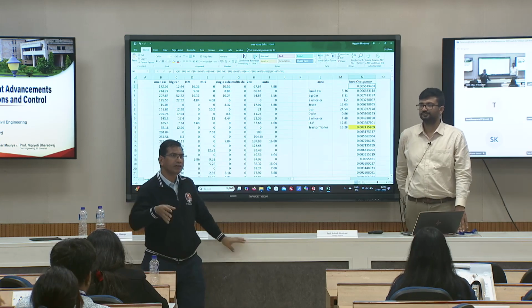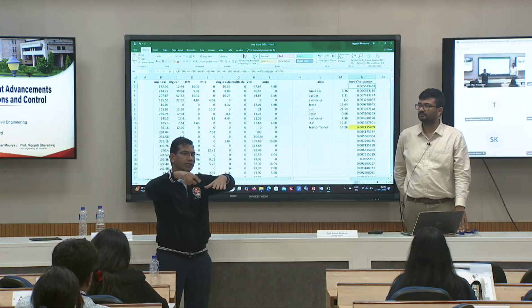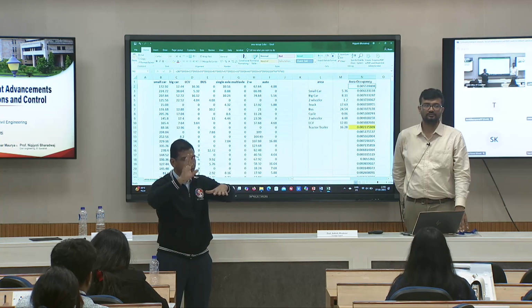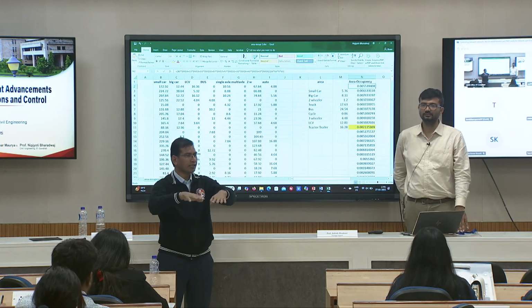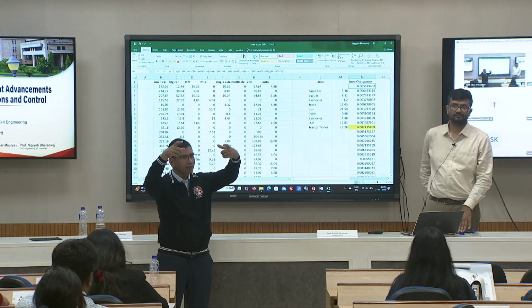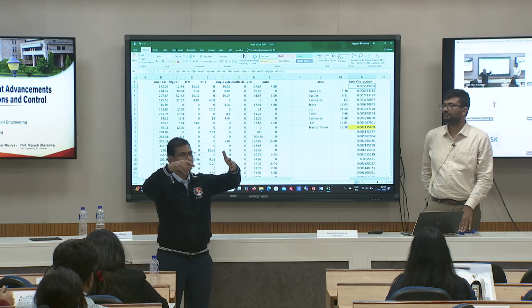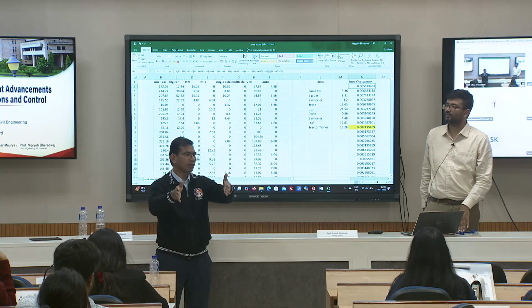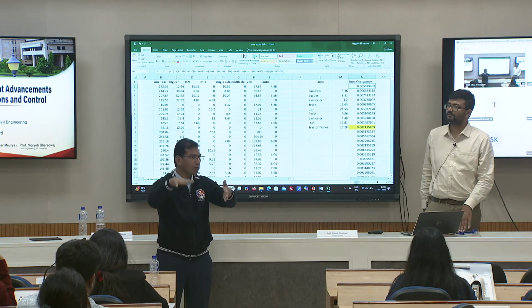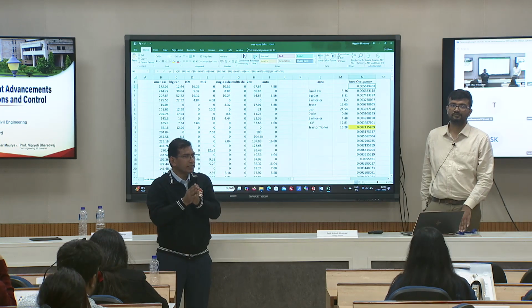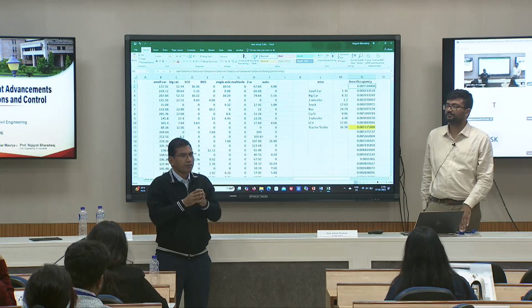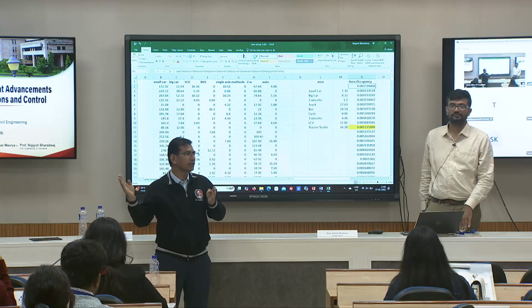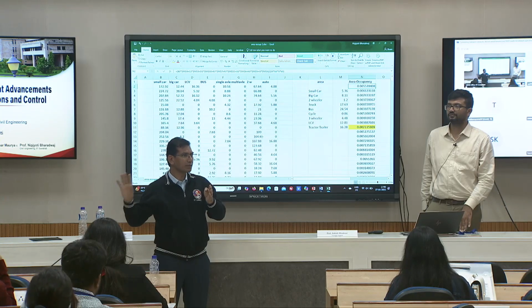What we are seeing is that if you see from the top, wherever you are not able to see the road, that is occupied by the vehicle. So if you keep taking pictures from the top, you can define the density level based on the area which is occupied by the vehicle versus not occupied by the vehicle. So now density is defined by this parameter, where you are avoiding the PCU concept, not neglecting it.